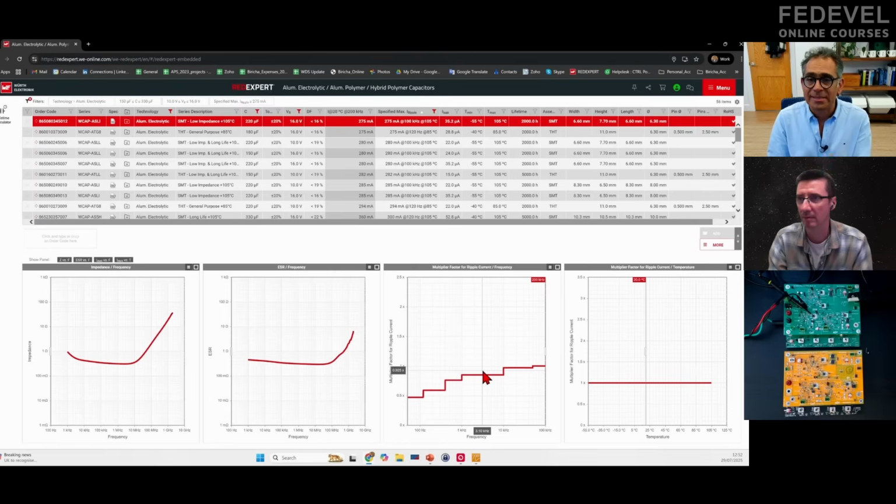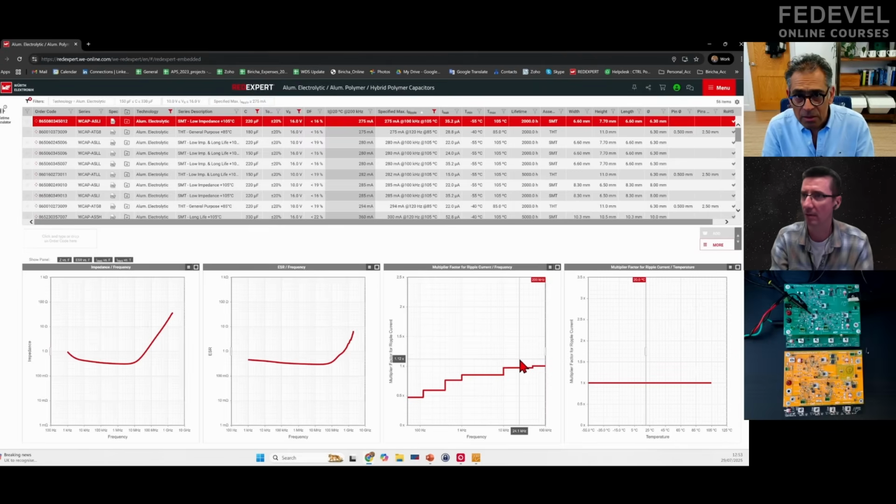So I have already set it to 200 kilohertz. But it's 100 kilohertz up here. I'm sorry? It's set to 100 kilohertz, no? No. Okay, it's specified 2 times, right? There's one specified here, right? It's really cool, this tool. Look, if I change the frequency, my switching frequency, it recalculates it and displays it there. Right?